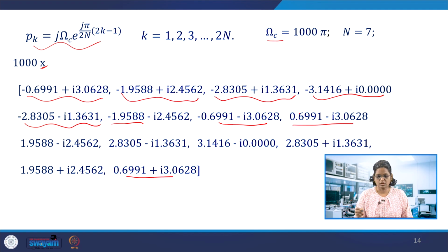So you can see the circle forming through these poles on the S plane. Similarly, the 1.8985 will have this replica, that is a mirror, and the conjugate of this can be a mirror and its conjugate. There are 1, 2, 3, 4 poles. So these two are conjugates, and these two are conjugates here.